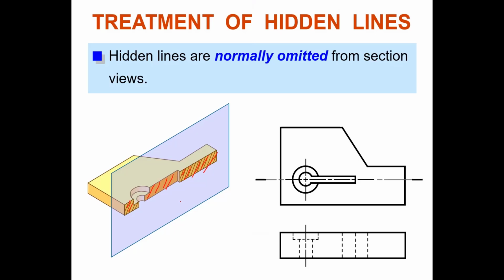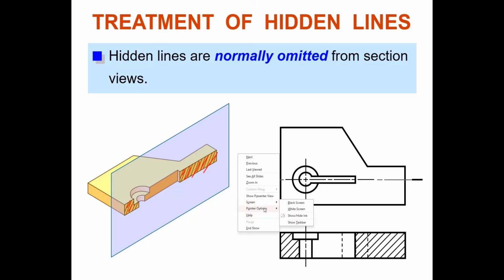The middle one is not hatched, right, class? The middle one is not there, because the cutting plane cuts only the surface that is involved in the cut with the plane. The middle can be shown by a visible line. So it is supposed to be like this, and you do the hatching. Can you see what is supposed to be a hidden line? So what is this hidden line? This hidden line, of course. Can you see? The hidden line is this corner. Clear, class?